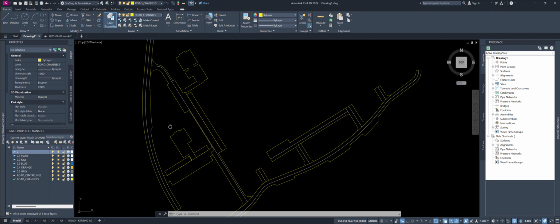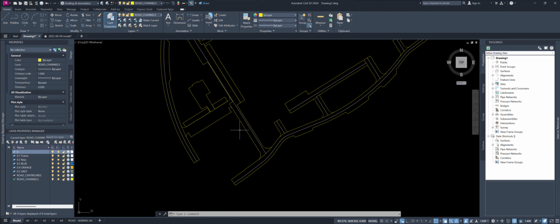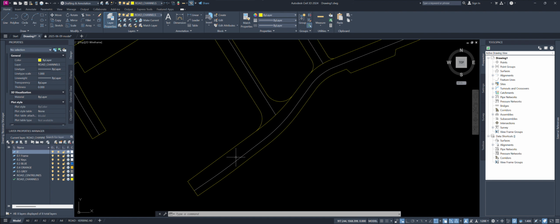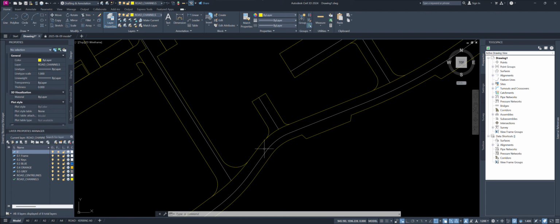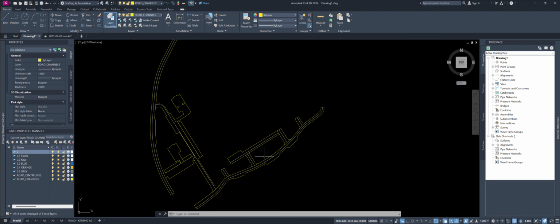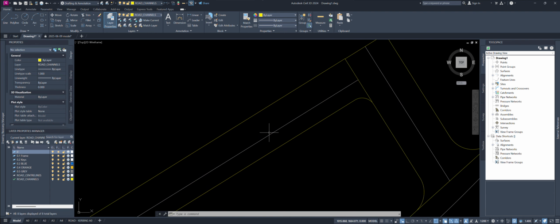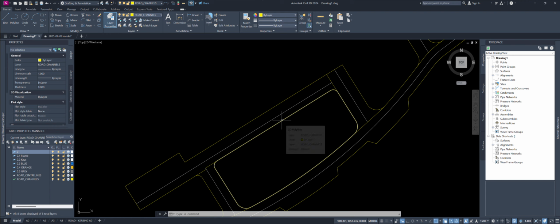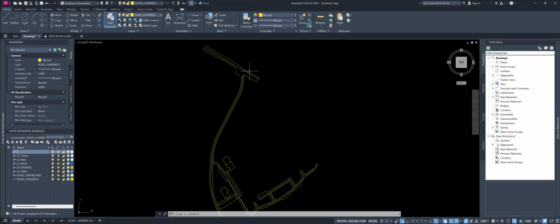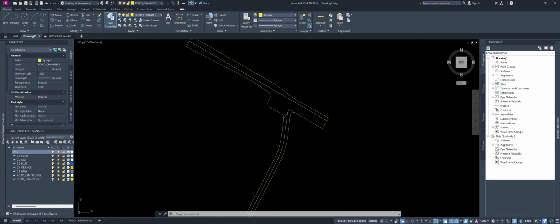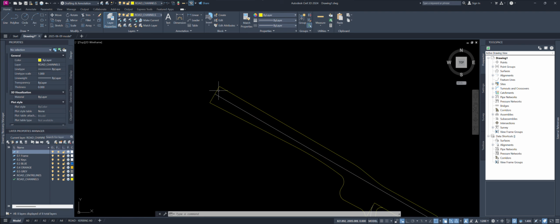With this instance, when you start setting out your roads, you're always going to be snapped to the left or to the right side of your channels, because we created a complete loop model. Apart from this bit over here, because it's an internal loop, so you have to snap to this one additionally. This is the only one. Everywhere else you are going to auto snap to the closest to your channel.